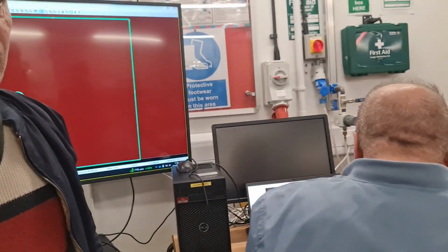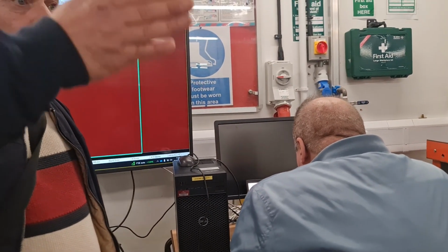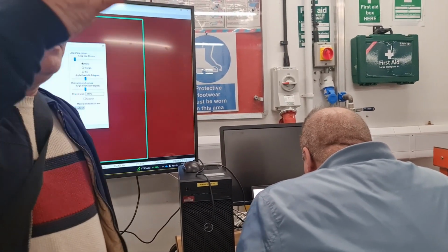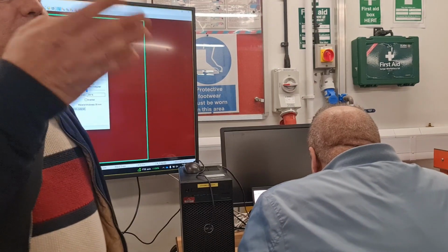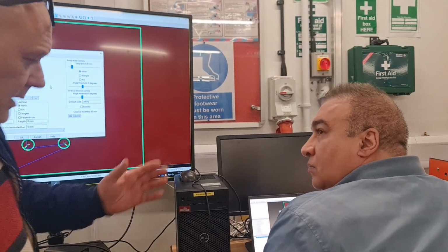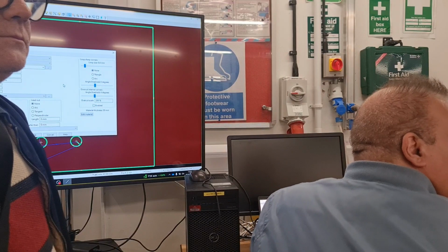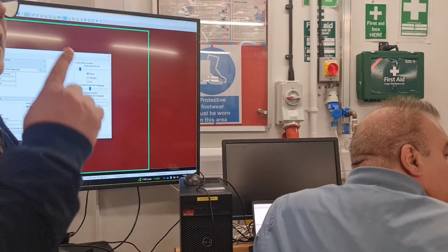Let's say you have a line that you want to cut with 0 offset, which means the kerf will be on the line. So if the kerf is 2 mil, for example, you have 1 mil on this side and 1 mil on that side. You can do that as well. But you couldn't say not to cut the square now. You would need to go back to your file.